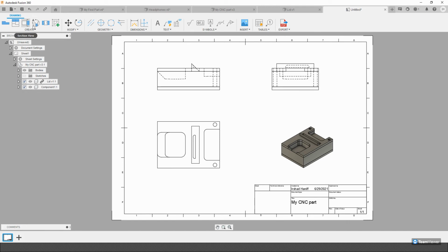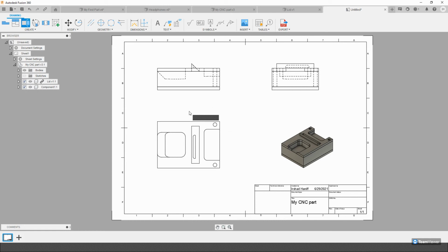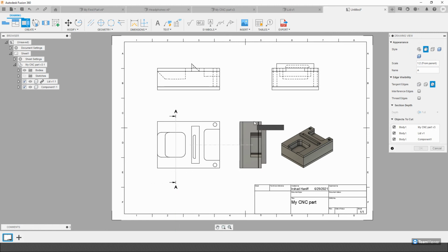I can make some cutouts, sections, or breakouts. So for example, if I look at a sectional view, I can say let's cut this in half, or maybe I'll do it cleverly so you can actually see a section. So I'll cut out from here to here. And you'll see here exactly what the sectional view will look like.